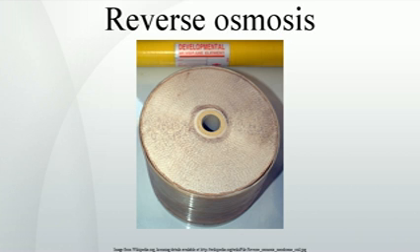Pretreatment in seawater reverse osmosis systems has four major components. Screening of solids. Solids within the water must be removed and the water treated to prevent fouling of the membranes by fine particle or biological growth, and reduce the risk of damage to high-pressure pump components. Cartridge filtration. Generally, string wound polypropylene filters are used to remove particles of 1 to 5 microns in diameter.